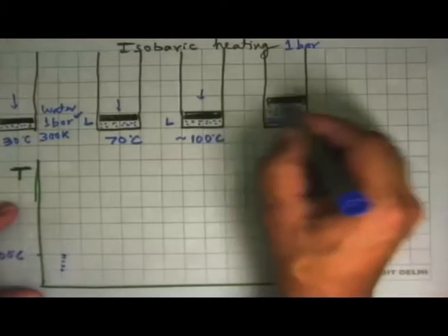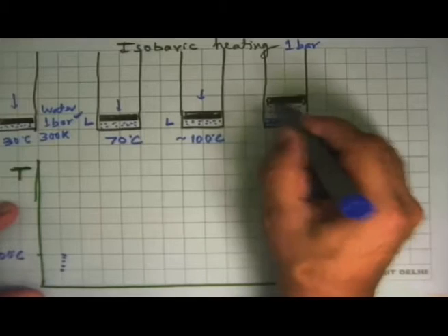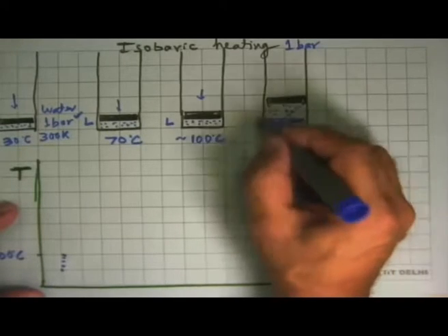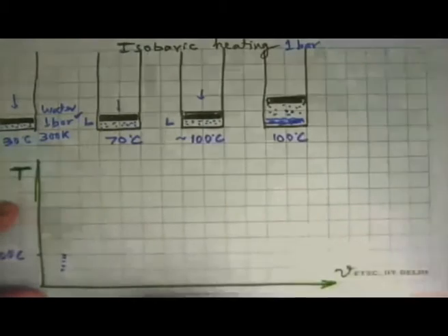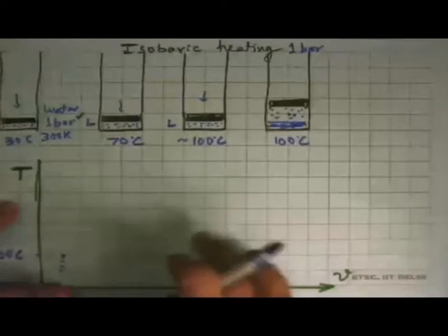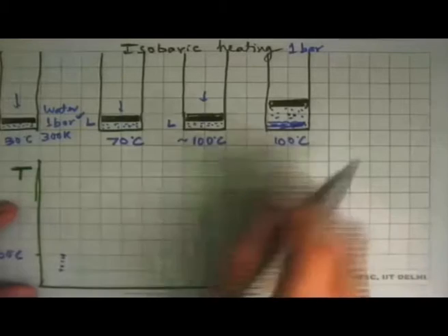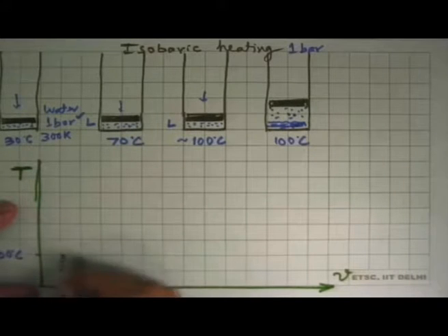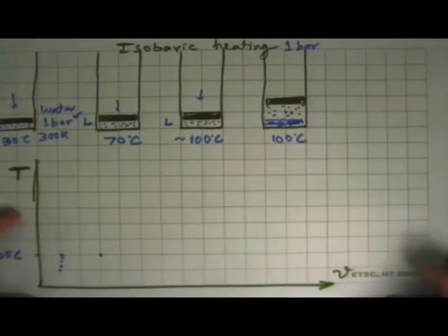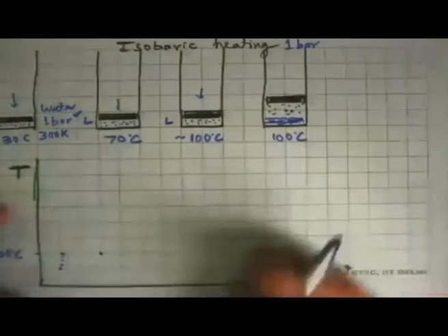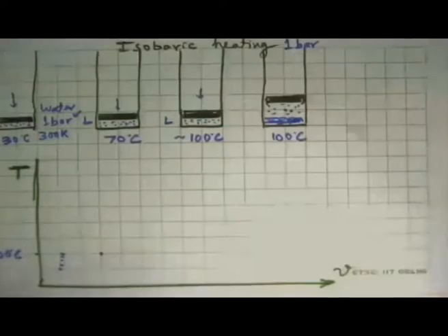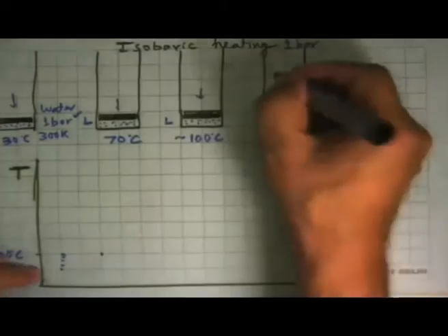So what we will do on this diagram is say, well, I'll just plot the total volume of this. So my mass is the same, volume has increased, so specific volume, meter cube per kg, that will increase and increase a lot without any change in temperature. So this state will now start moving along the 100 degrees Celsius line and say come over here. Then we do more heating, and what we'll see is that the piston goes up further, so it comes to another point here.